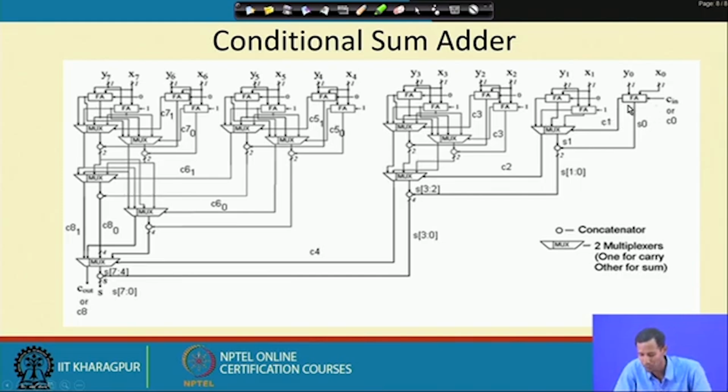Whenever I compute one cell, I am also computing the other, as all the inputs are already available. So these two full adder cells run in parallel, one with 0 carry and the other with 1 carry. In ripple carry addition or any other addition, the previous stage generated carry affects the current stage.